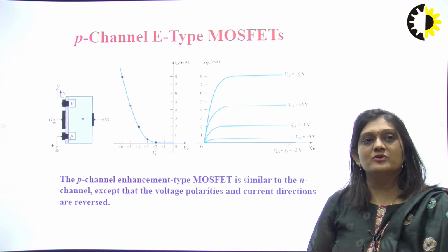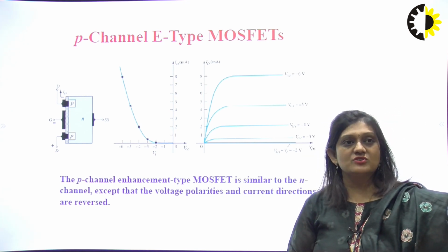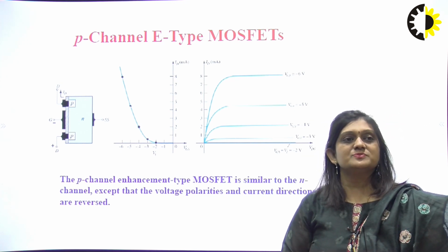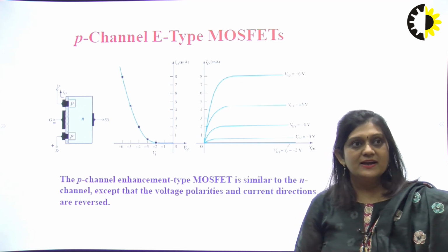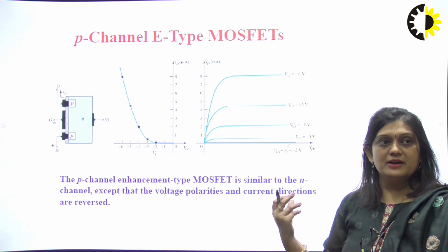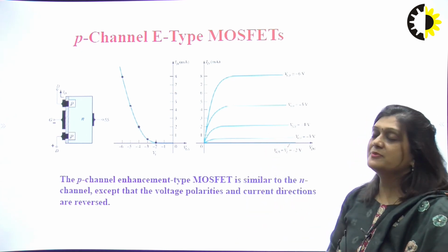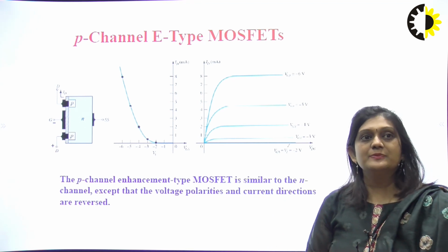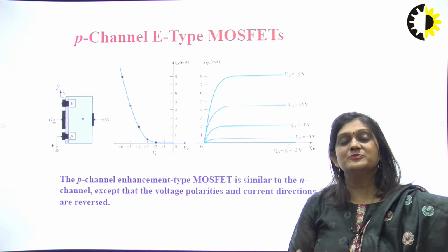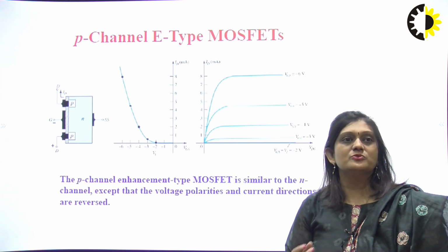Okay, in this lecture, we have studied the depletion type MOSFET and enhancement type MOSFET. In enhancement type MOSFET the channel was not there, and the induced channel was made with the help of the VGS voltage, and in depletion type MOSFET a channel is there in between both blocks. Enhancement type MOSFET works in only one mode, and depletion type MOSFET works in both modes. Thank you.